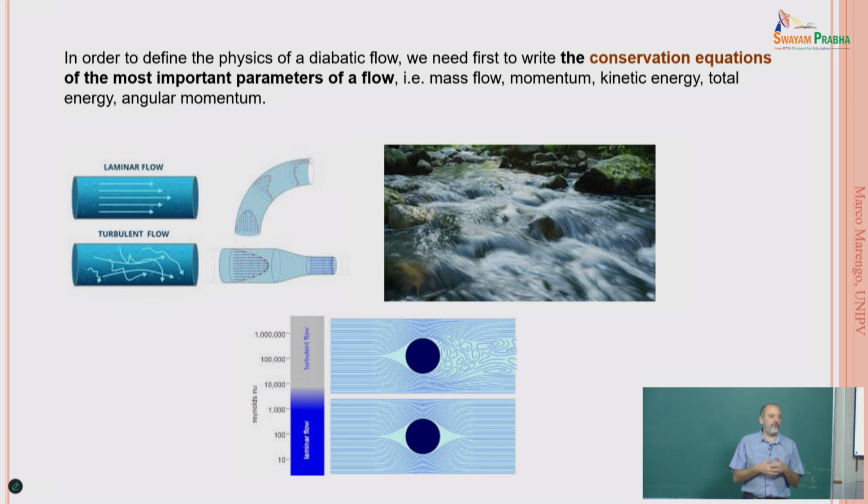When we have a turbulent motion, we measure in one point and we have a chaotic situation. Measuring one point, in time we have an oscillation, chaotic conditions, and it is not easy to have a prediction of what is happening afterwards. In fact, it's not possible to predict at a very short time. We need to wait a little bit to average the motion and understand what could happen in terms of fluctuations, the intensity of fluctuations, and the average value of the velocities.